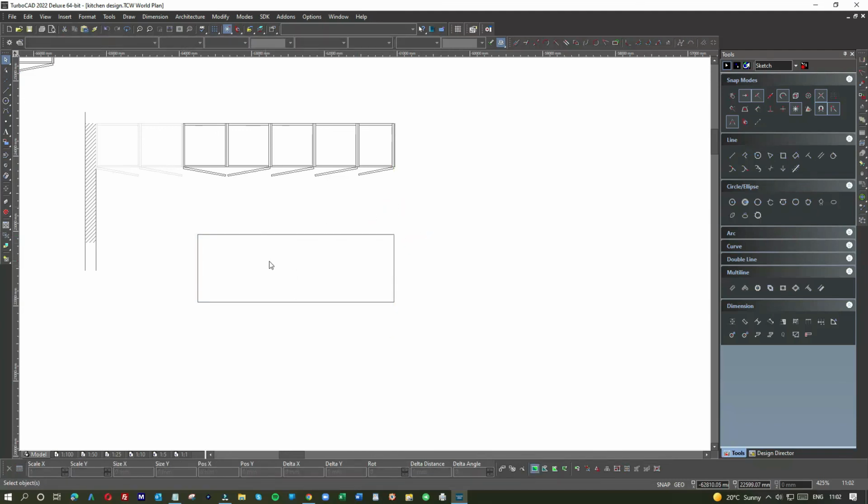In your island maybe you're going to have a kitchen sink, but what I was really showing you was always keep this distance 1100. You might make it 1050 if you're pushed, but 1100 is better. And that applies all the way around, so you have proper clearance.